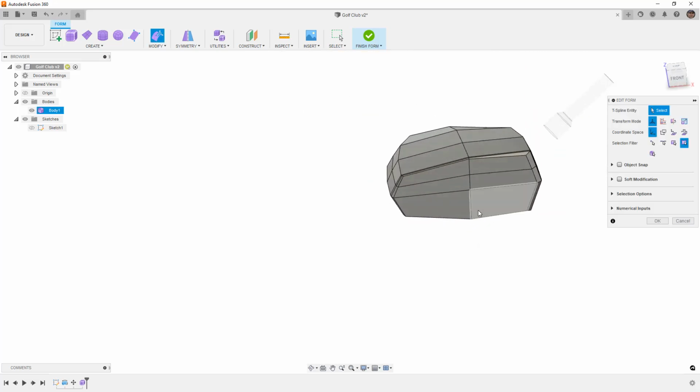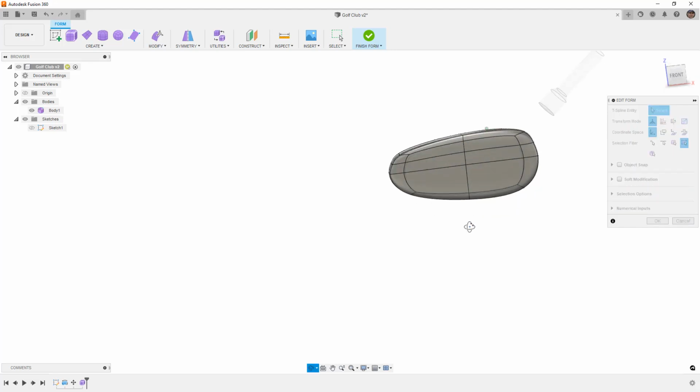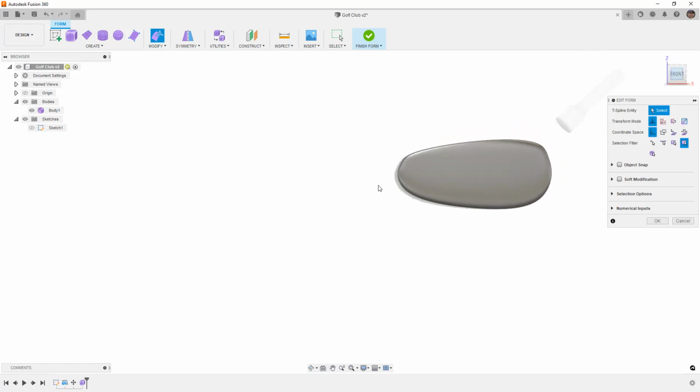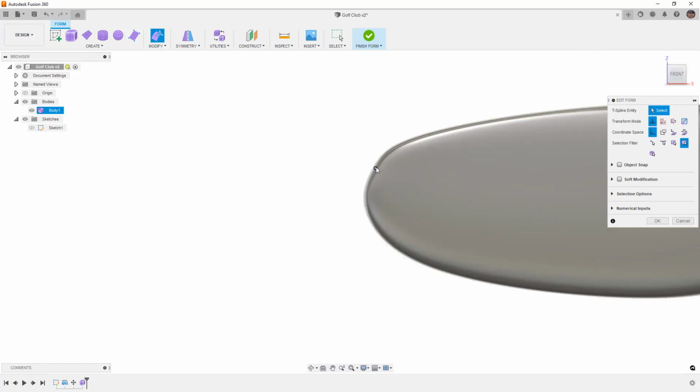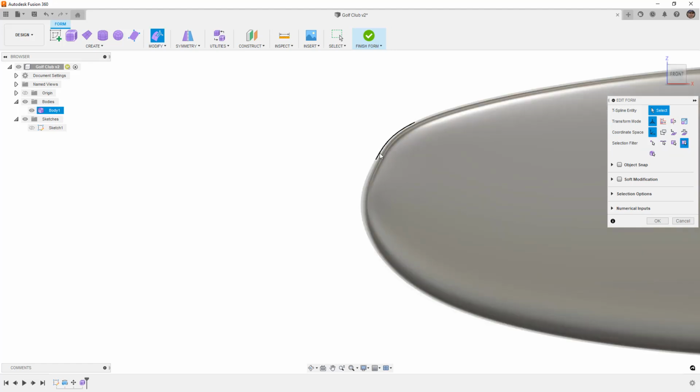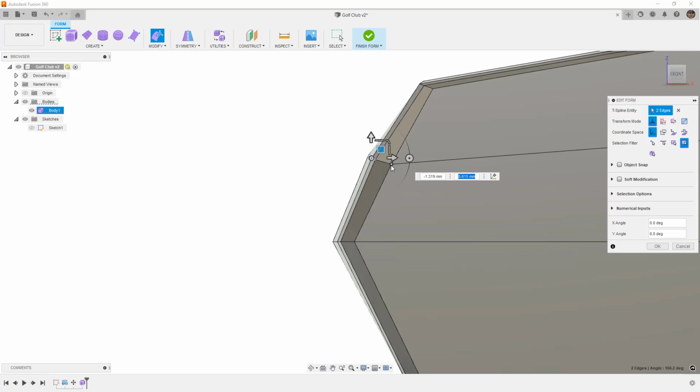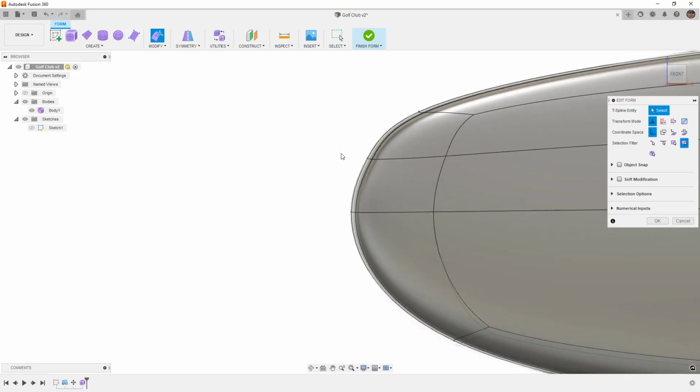All right, so now that we got that midline in there, I'm going to take a look at this in smooth display, Control and 4 to hide my edges. Now, what we're seeing here is we've added this extra bump in the shape. Now it looks like it's bumping in and out, and part of that is because of this right here. This is not drastic enough to prevent that from happening. You can see here if I move it out, it looks a little bit better.